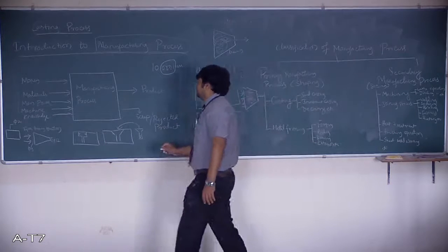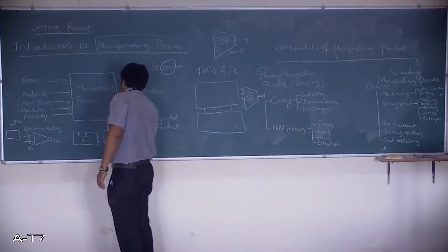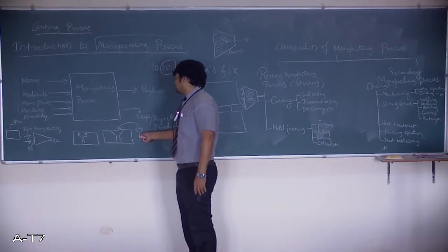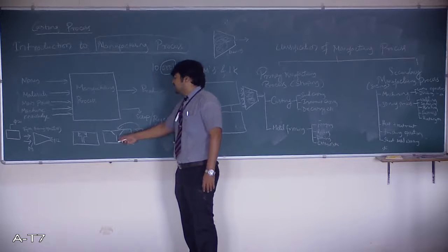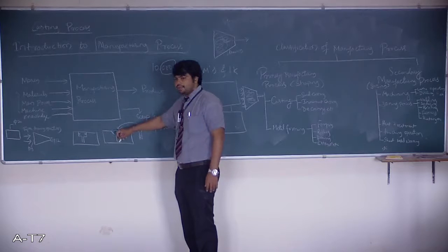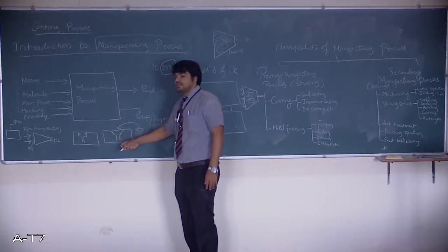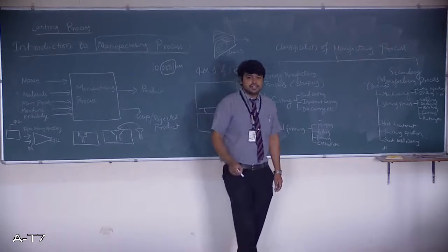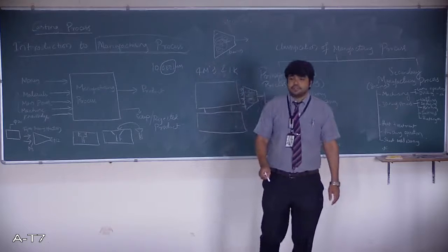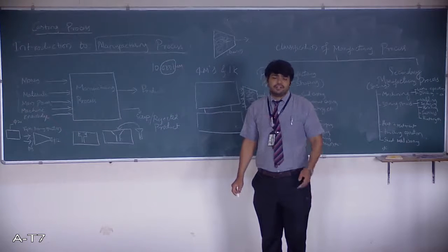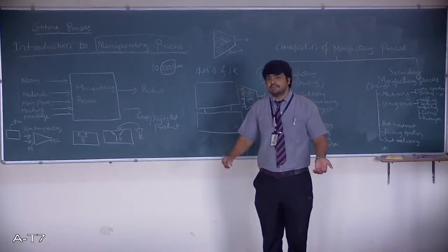Also, I can make threads over here. Threads are the external grooves on the screws, and when we insert this, you require a grip, so those threads can be made internally for this particular hole. That is what we call the tapping operation. So these are different operations we perform. Apart from that, there is a milling machine, there is a shaping machine.